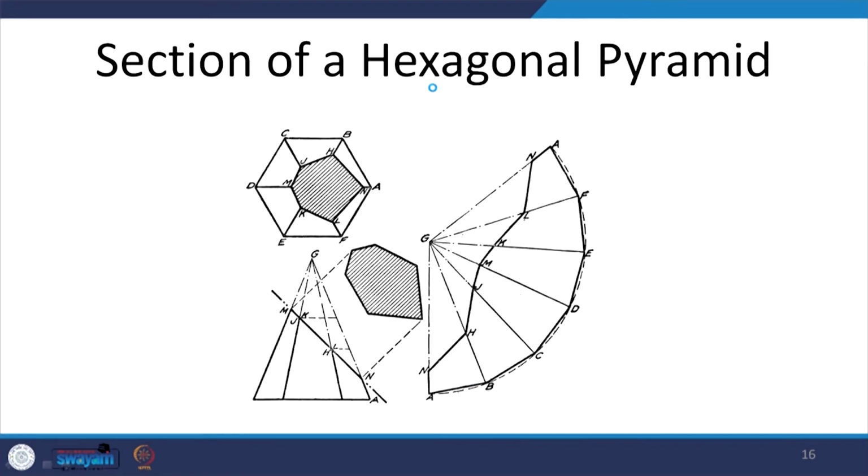Very simple. If you have already understood the process for cylinder and cone, making it for these different shaped pyramids is definitely easy. Same thing here, hexagonal pyramid. We have the hexagon in the base, same 6 edges, 6 equal triangular surfaces, different heights which we will get here, and in the bottom we will have the hexagon, and in the top we will have this true shape.